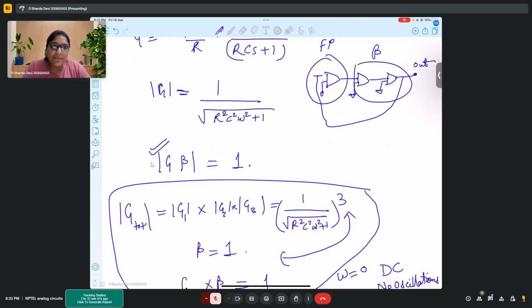So this condition is never satisfied, no matter which op amp you consider in the forward path and which in the feedback path. Because if I take my output from here, then the remaining part would be my feedback path. The idea of feedback is that wherever you feed your output back to the input, that path is feedback, and the remaining part is feed forward. In the Barkhausen criteria, you analyze the complete circuit, no matter where you take the chunks from, because you analyze the feed forward as well as feedback paths together.